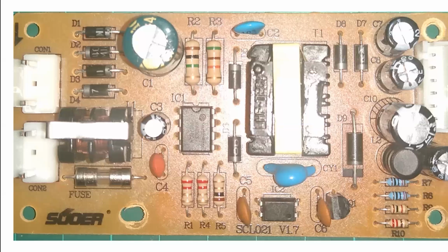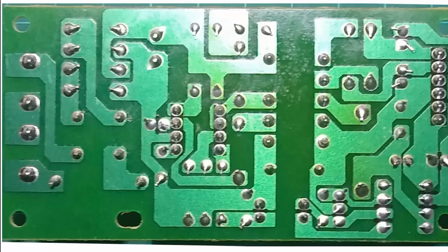So as I say, we went through that in great detail a moment ago. If we turn it over and look at the other side, there's that gap right down below the transformer. Not only have I turned this over, but I've turned it over around a horizontal axis so that the mains is still over to the left. And you can see the 2 mains connections in series, so it doesn't matter which one goes to which. There's nothing to see here really. It's all single-sided, lots of copper to let the current capacity work. There's no shorts, no bad joints, nothing like that.